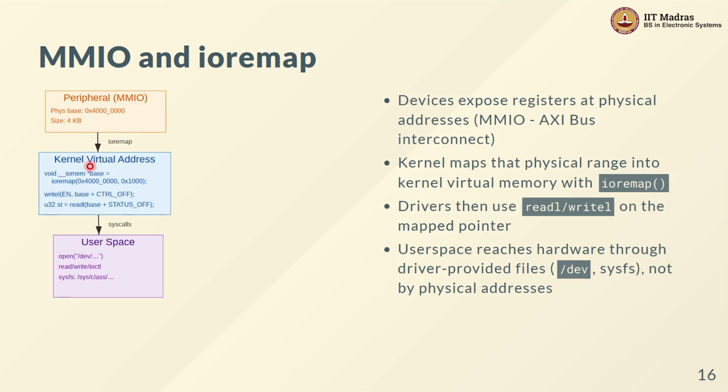Now, you might notice one extra thing out here. When I declared base as a pointer, I also used this __iomem. This is an attribute which is specified as part of the C language, which basically says that this particular pointer needs to be declared as an IO type pointer. What makes that special?